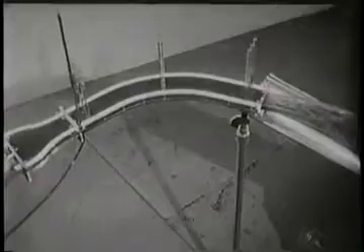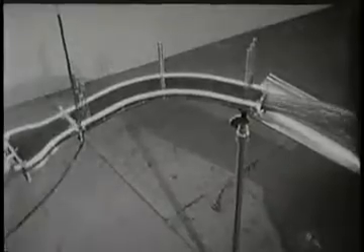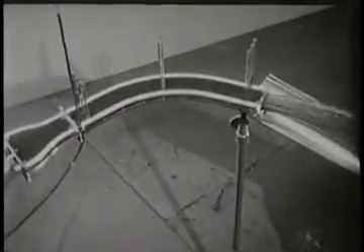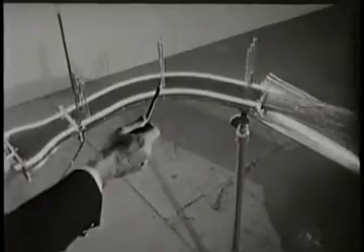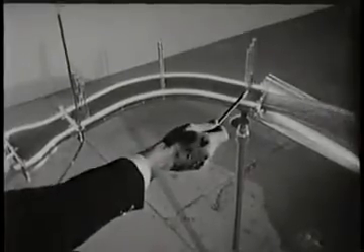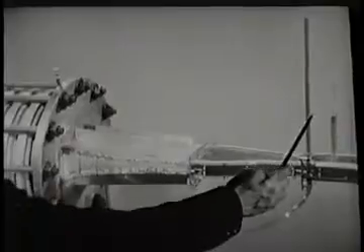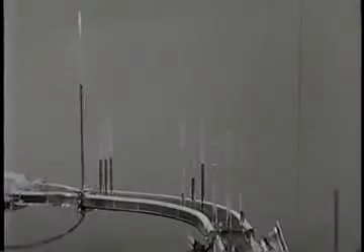This is a set of 3 static pressure manometers in the straight section approaching the bend. This set is in the middle of the bend, and this set in the straight section following the bend. In the upstream straight section, the streamlines are virtually straight, and the 3 manometers show no pressure variation normal to the streamlines. This tall tube shows the stagnation pressure in the large upstream settling tank. The difference between this stagnation pressure and the static pressure at the upstream tubes gives a dynamic pressure of about 11 inches of water.